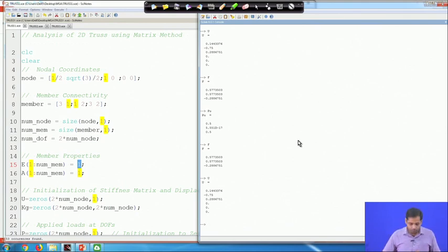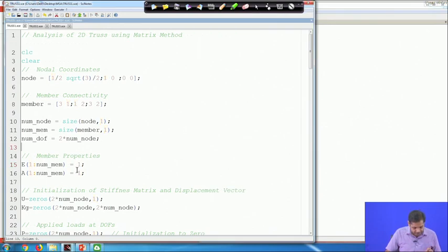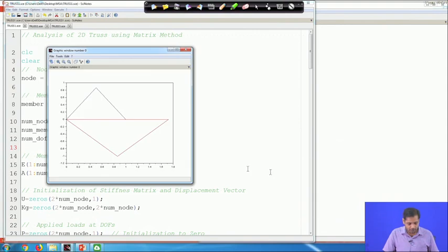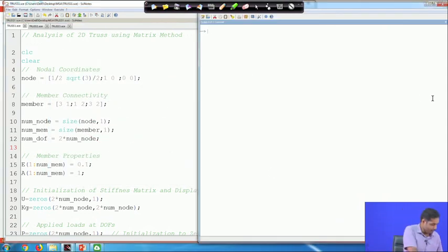Okay. Now, let us check the Young's modulus. Instead of 0.1, you make it 1. If you make it 1, what will happen? If you see, the displacement is 7.5. Okay. So, which is obvious. What we are discussing is a very obvious thing, but through this check, you can check whether your results, your codes are correct or not.